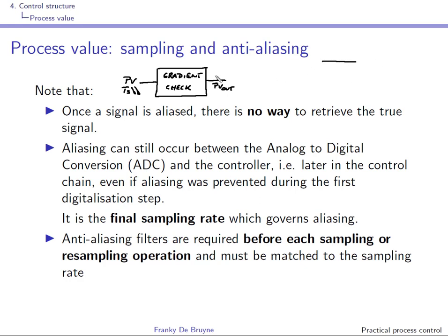Well, suppose that this PV is used for control. This will be, for instance, a PID control. Let us assume that we're doing tracking over here, so we have a tracking problem. Well, you should look at the rise time, right? So you can look at the step response. We look at 90% of the steady state response and 10% of this steady state response. This will be somewhere over here, this will be somewhere over here. So this is the rise time, and since we have taken TS so small, we see here, oh, we have too many samples in a rise time.